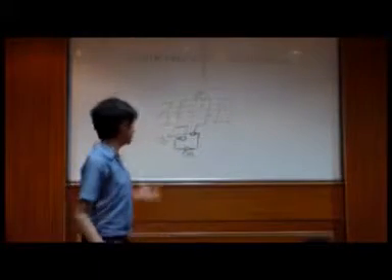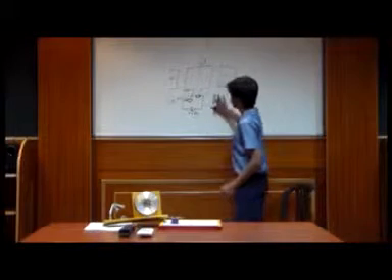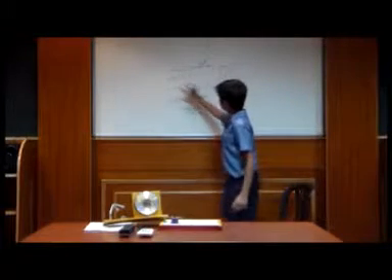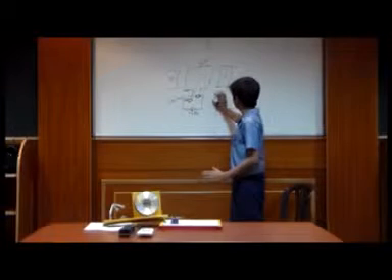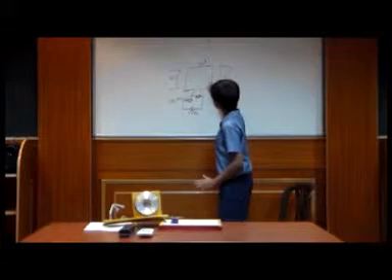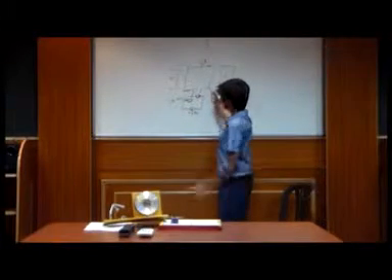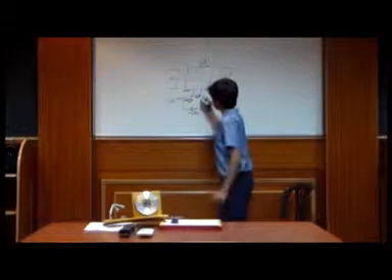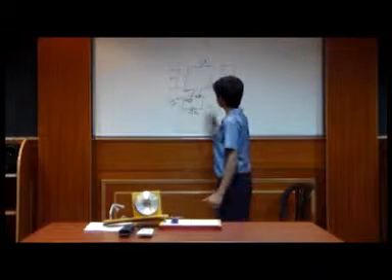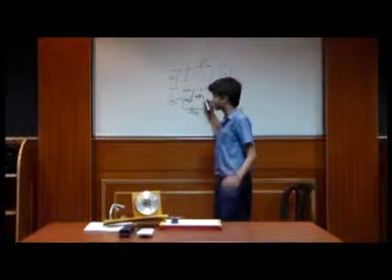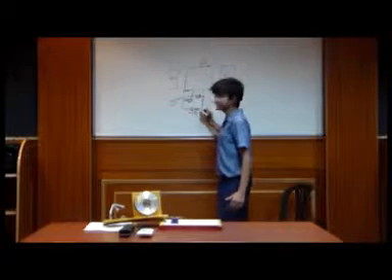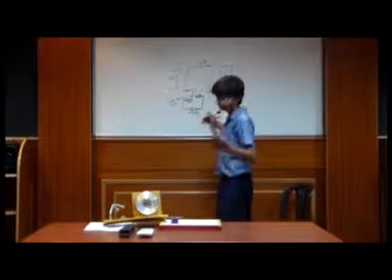The million dollar question is, how does current get induced in the generator? To understand this in a better way, we have this diagram. Here we can see in the diagram, these are two pole ends of the magnet. This is called the armature coil, which is free to rotate. These are called the slip rings, and these are basically to conduct electricity. These are connected to a galvanometer to see the current.